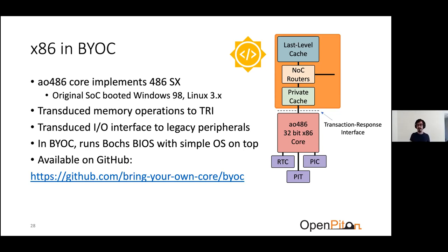And what our students did was build ways of transducing from the AO486 core's memory interface into BYOC using tree, right? So the first thing we'd done was using the Avalon interface that it provided natively, and then we moved on to using the native interface, that it was already transducing from a native interface to Avalon. And so in the BYOC environment, we can actually run the real x86 BIOS with some code commented out that we don't actually use. And we can run a simple OS on top of that, simple boot sector programs on top of that as well. And we keep around the existing legacy peripherals like the clocks and interval timers and interrupt controller.